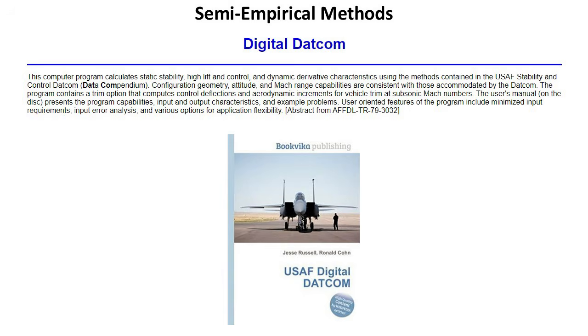So using fundamental aerodynamic theories such as potential flow and boundary layer theory, a semi-empirical model can establish a basic framework model incorporating empirical corrections and coefficients to account for complex real-world phenomena that are really difficult to model purely from first principles. Prediction codes like DATCOM that rely on experimental data and aerodynamic theory can be used only if a significant aerodynamic background is present in the user running the code.